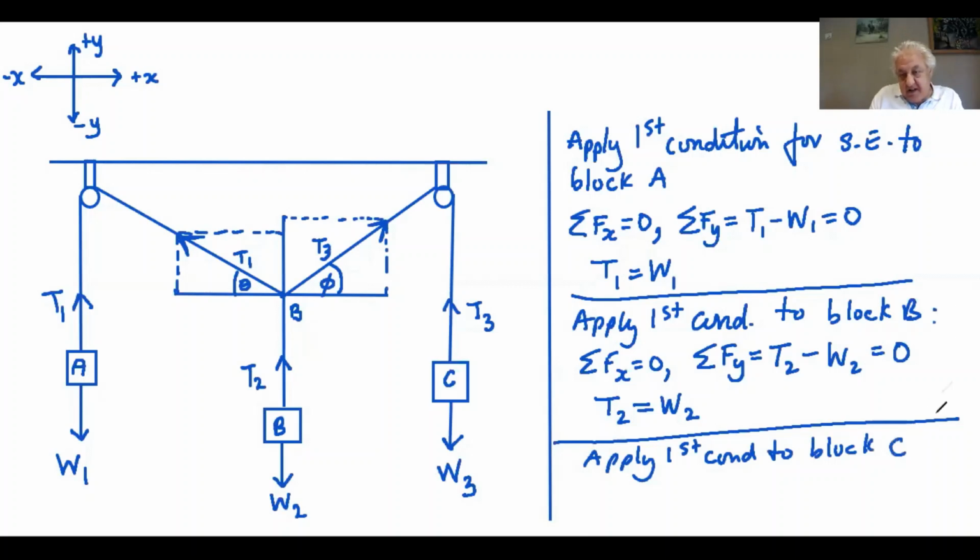All of this we can get just by intuition, that we know the force is balanced. Again, there are no x forces. My sum of the y forces, T3 in the positive direction, W3 in the negative direction, equals 0.